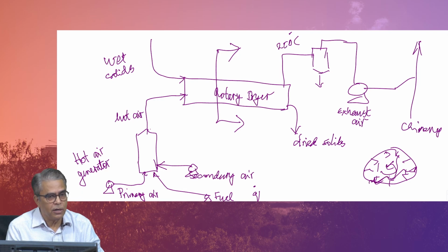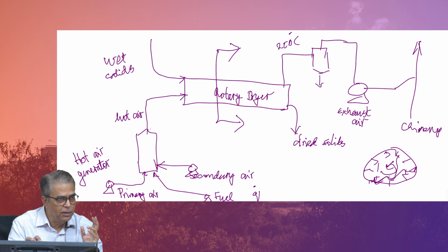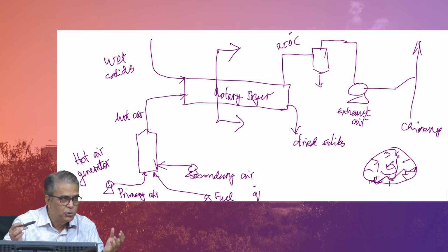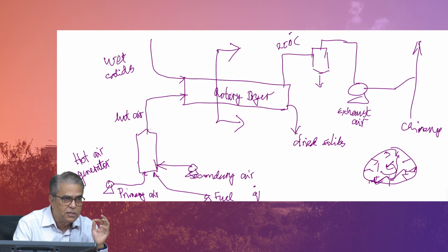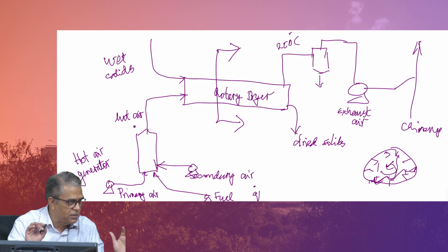Now, switch to that rotary dryer. For the solid to get dried from this to this moisture level, you require some air to flow through. How to find out that air flow rate? Two things will happen. One, the air that is entering should have sufficient energy to dry the solids and also heat the solids. In the heat balance, solids are coming in at some temperature, getting heated up to some other temperature. The moisture content in the solid is getting removed, that is why the solid is getting dried. So, these two will define the heat balance of the material. If you compare that heat balance with this, you should know that heat is actually generated here, so that it can be transferred there, assuming 0 losses.